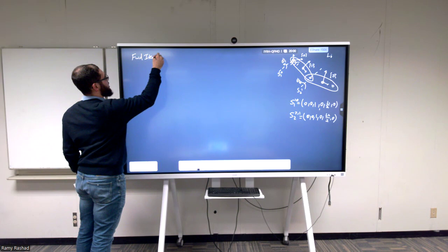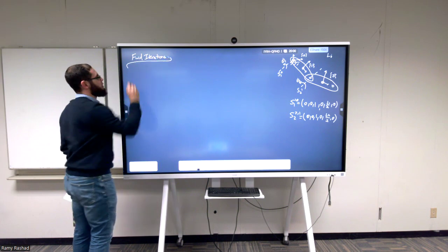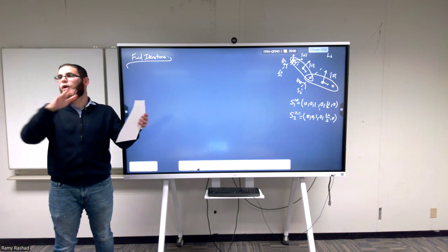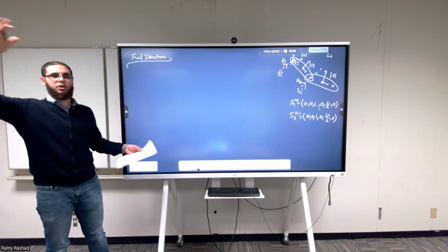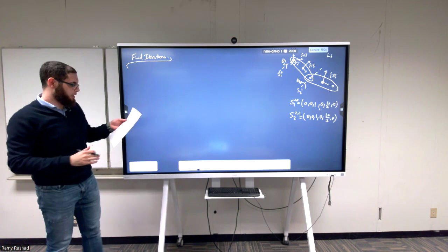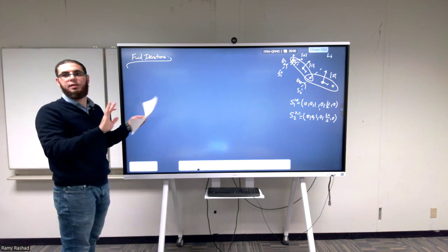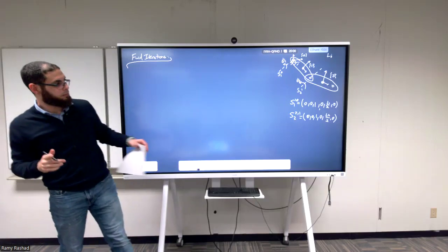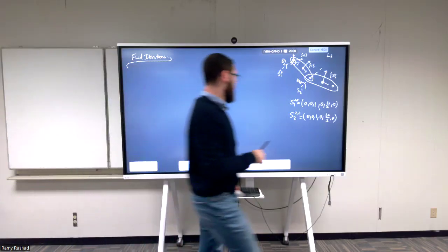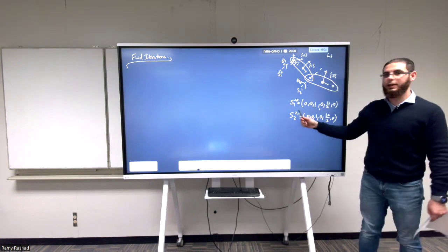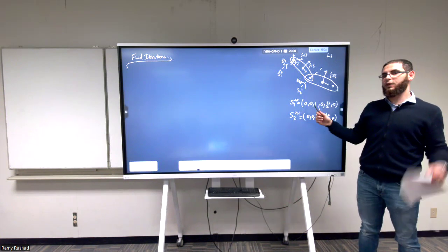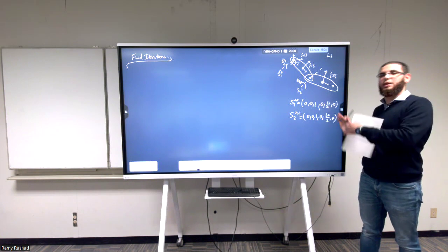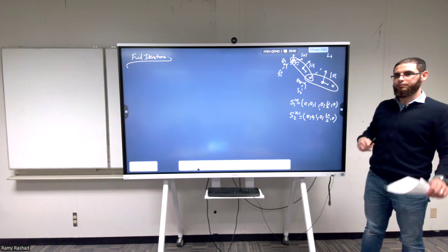What I'm going to do now is rewrite the equation that we had in terms of i and i minus 1, and everything just in terms of 0, 1, and 2. We're just going to expand the 5 equation that we had into 10 equations. Question? No, because this is 2 with respect to 1 expressed in 2. This is different from what we did in the first lecture when we talked about the product of exponentials of everything with respect to 0.